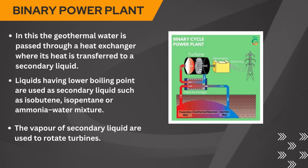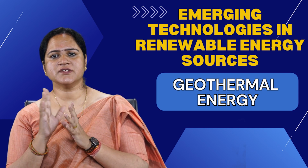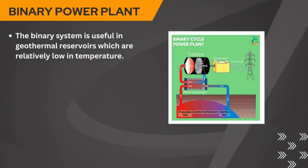The vapor that is produced from this secondary liquid is used to rotate the turbines. So the steam that we are going to utilize here is generally the vapor of the secondary liquid. Other secondary liquids we have already discussed. So this binary system is very useful in geothermal reservoirs because they are relatively low in temperature. Okay, so this system is generally useful for the geothermal reservoirs.